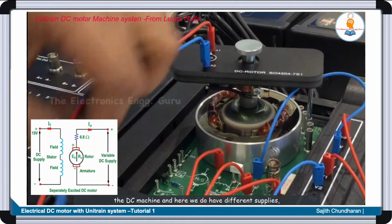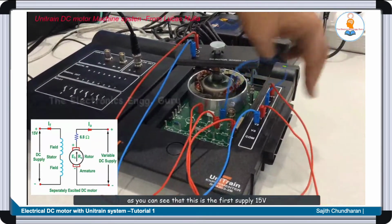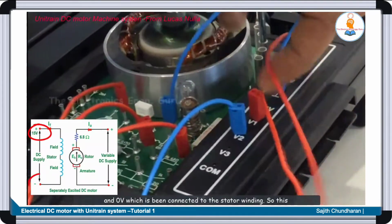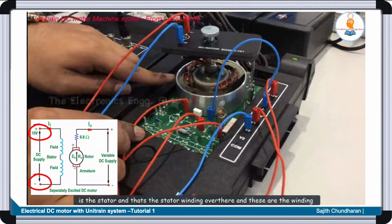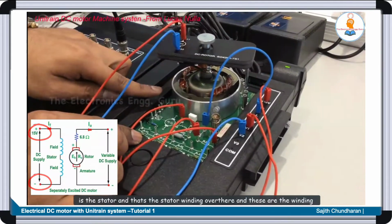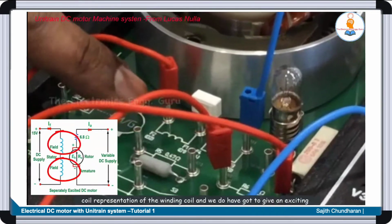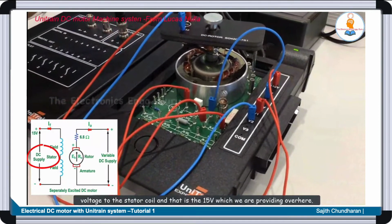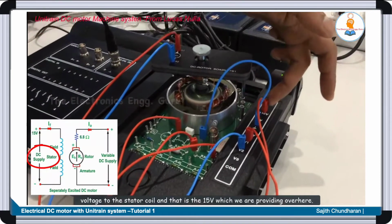And here we do have different supplies. As you can see, this is the first supply, 15 and 0 volt, which is being connected to the stator winding. So this is the stator, and that's the stator winding over there. And these are the representation of the winding coil. We have to give an exciting voltage to the stator coil, and that is the 15 volt which we are providing over here.